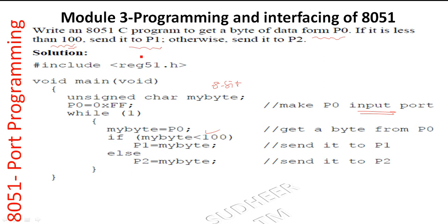So if you want to implement this with an assembly language program, it won't be as simple as these simple statements. We cannot implement this with such a simple statement. We need to bring the data to the accumulator, then to another register. We need CJNE, compare and jump if not equal, then jump on carry; such instructions we need to use to implement this program, and then you may feel it is quite difficult.